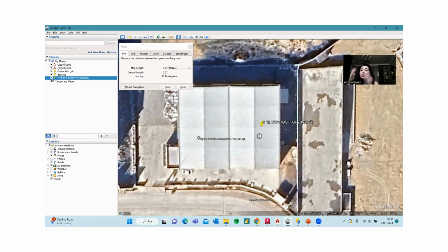But there is a crucial point: we are not able to take this 306 degrees and simply paste it into PVsyst. The explanation is that the coordinate system of Google Earth and the coordinate system of PVsyst are different from each other.